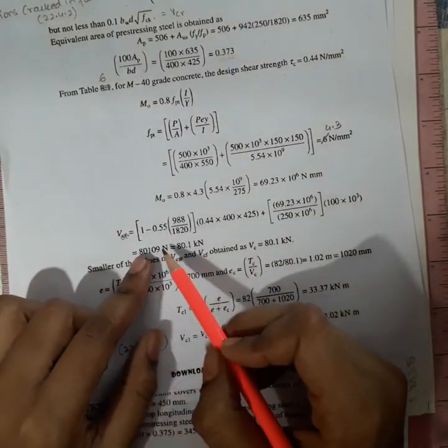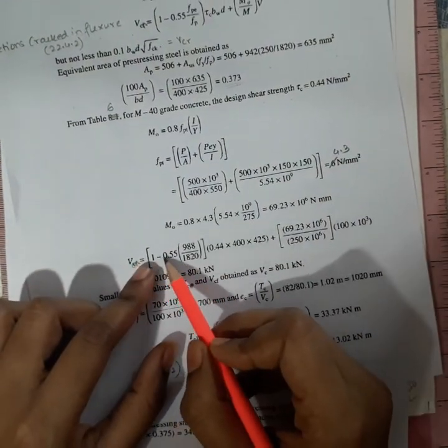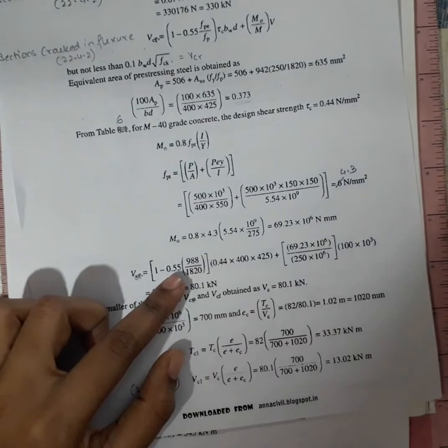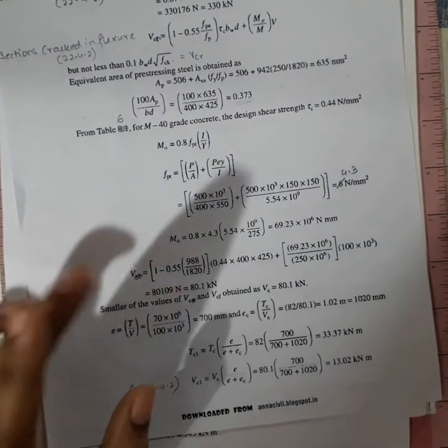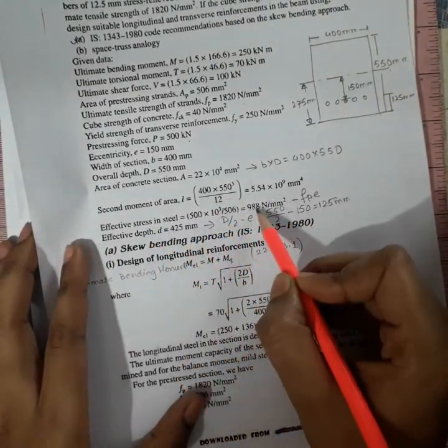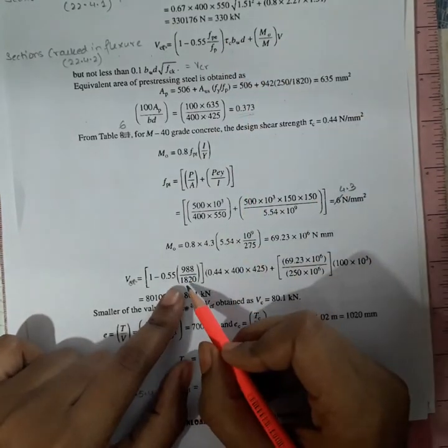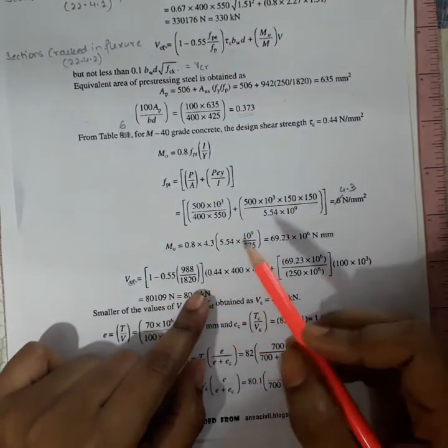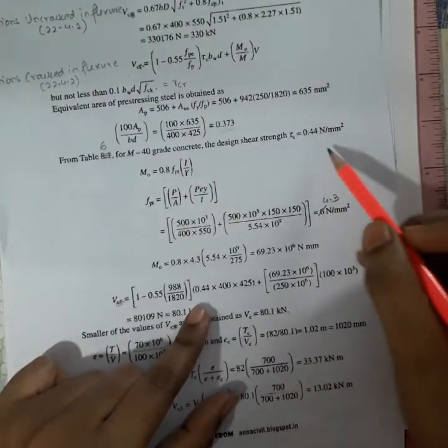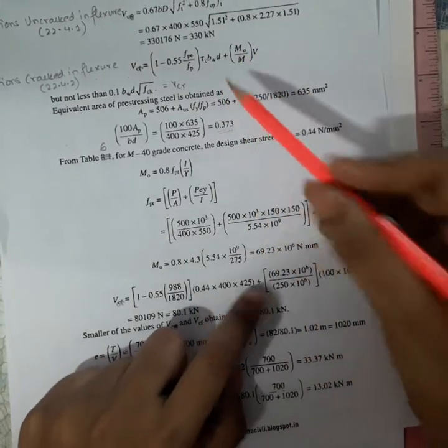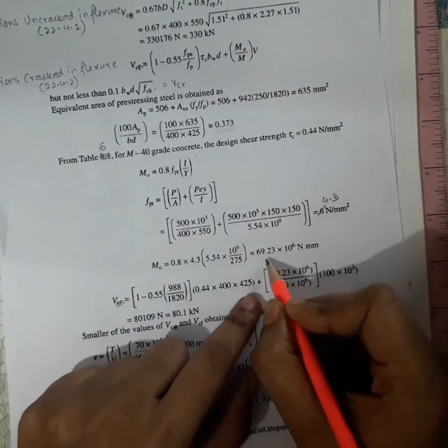Now putting all the corresponding values, 1 minus 0.55 FPE. What is FPE? It is the effective pre-stress after all losses have occurred. So we have already calculated this earlier as 988 Newton per millimeter square. So this is the value divided by the FP, which was given as 1820 Newton per millimeter square, into here tau c is 0.44 into B 400 into small d 425 plus m naught. We have calculated it to be